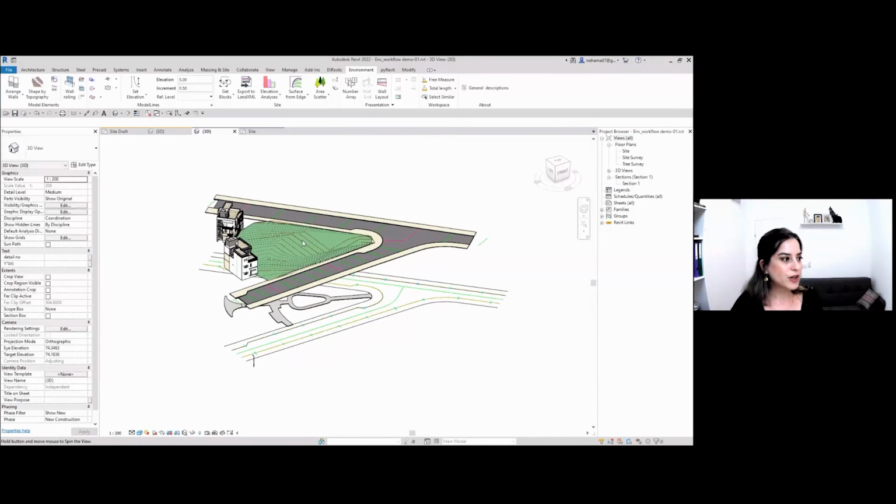model over here. Let's go to plan view and just see a couple more comments to just finish up and make it into a really good document, right? A really good plan view. So what I'm going to do now, I'm going to show you another really nice command that's called slab contours. And what it's doing is exactly what it promises to do. Let me select all these floors and click finish. And now it's going to assign contour lines onto these slabs.